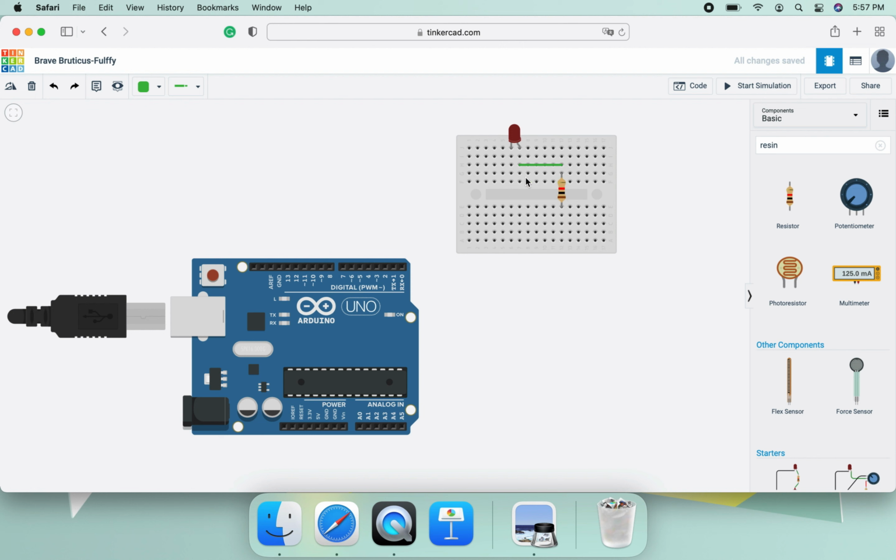Now after this one we need to connect the whole circuit to the Arduino. So for that we will first need a wire here on positive terminal. So just click on any of this vertical line port. There we go. Now we have a wire. So stretch it up to the pin number 3. There we go. And then when you click here you will get a node as I have told you earlier. Now take it to pin number 3 and click here. There we go. So we have connected this resistor to pin number 3.